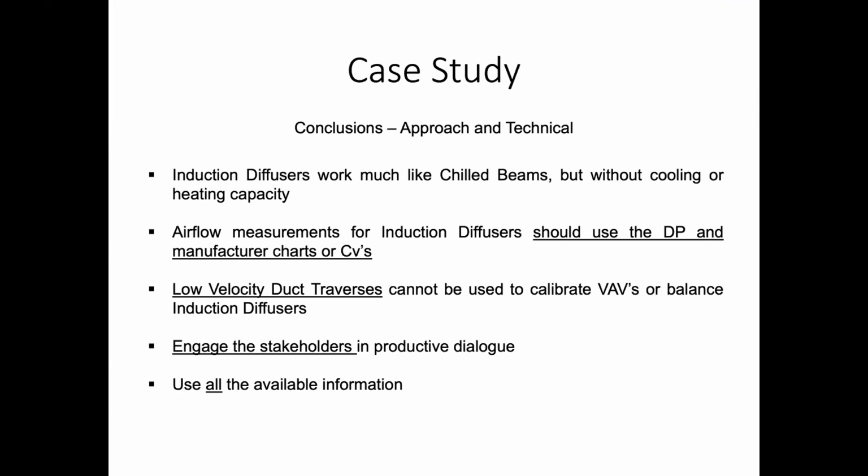One says, I might have missed it, but what is the discharge air temperature from the AHU? In this case, I believe it was either 48 or 49 degrees. 49 degrees, because there was a 6 degree difference. So this one they were using 49, but in reading it, they do have applications where they'll go down to 45 and 46 degree discharge air with induction diffuser technology. So it depends on the application, but here it was 49 degrees.